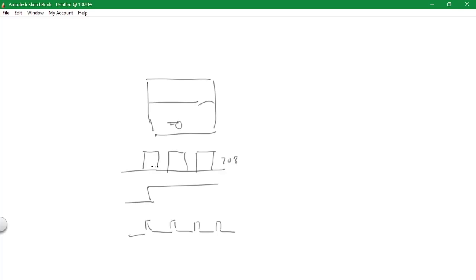So this has harmonics in it. It has your DC waveform, but it has harmonics. Any periodic waveform, other than a pure sine wave, has harmonics in it. So this has harmonics that basically go high in frequency, and because this has got a capacitor, high frequency lowers the impedance, and that little capacitor sits there and gets really, really hot. So you would never do this.